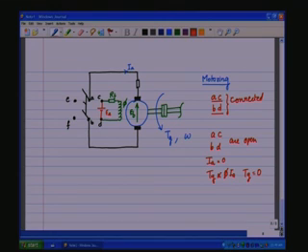Like if you are traveling in an automobile, if you switch off the engine, it will still continue to move because of the momentum, because of the inertia which is stored in the mass of the vehicle. So, we just allow it to gradually die down, there is no torque applied. On its own, because of the frictions associated in the bearings and so on, the shaft will coast and gradually come to 0. Now, that may take quite a long time depending upon the amount of inertia which is there on the shaft. Now, that is called coasting mode.